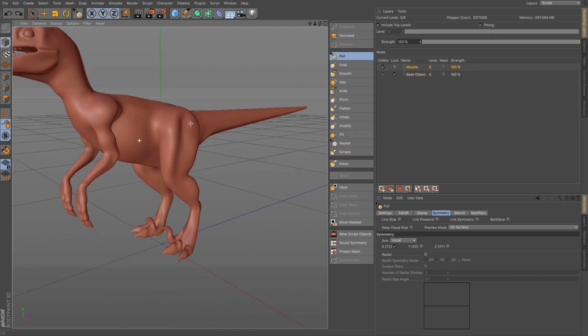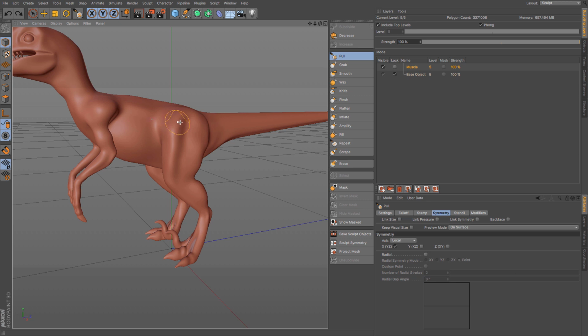Because the cool thing with the sculpting button is that if you paint, you can see that it bulges out. If you hold down Command or Control, it will invert the function so that you can indent. That's a bit much. The other one I'm going to use is smoothing, but you need to make sure that you link the symmetry when you swap the tool, because the symmetry is only going to be related to the tool that you are on.